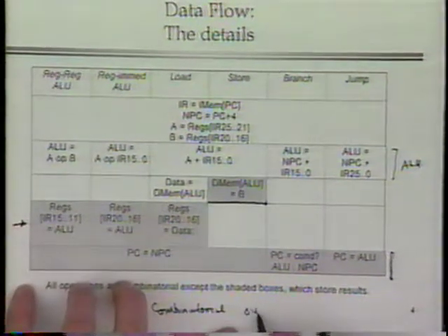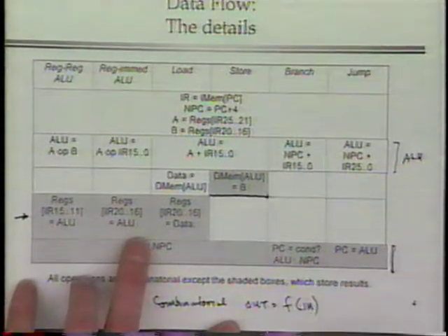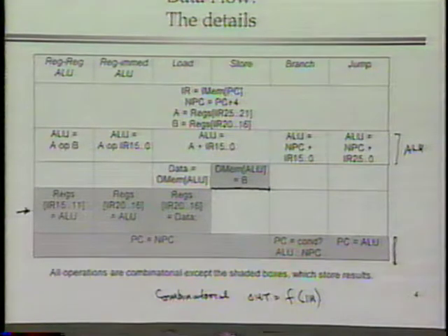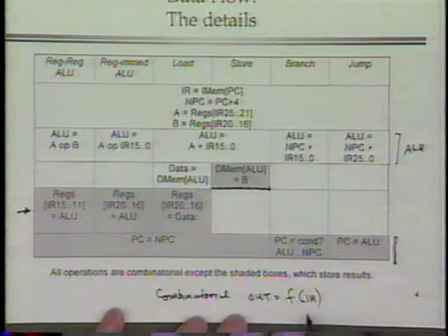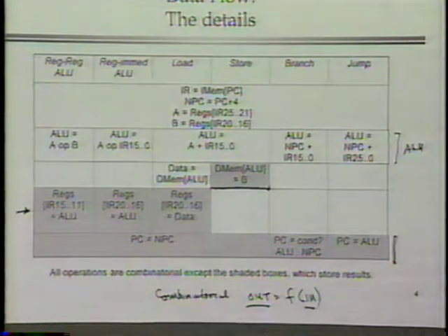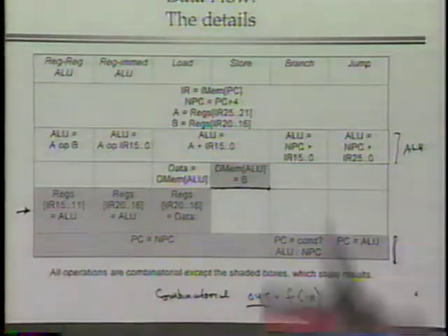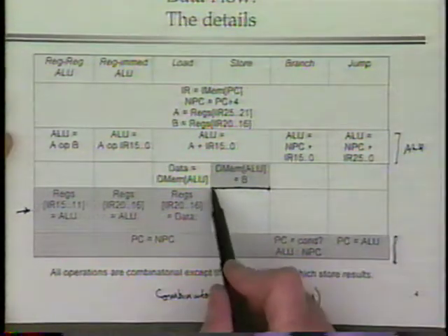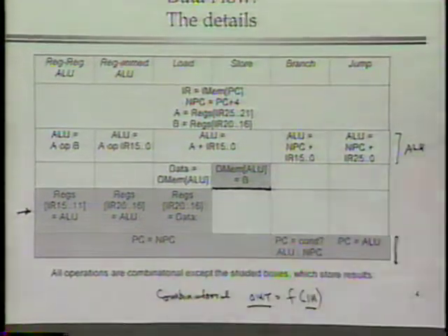is logic that is simply ANDs and ORs, basically. It's logic where the output is a simple function of input, and there are no clocks. There are no timing signals that are part of that combinational logic, and there's no storage as part of that combinational logic. It's just a function of the input that produces an output with no value stored and no clocks to indicate when things should happen. It's just sort of a bowl of spaghetti, and you drop things in the top and eventually it drips out the bottom. And the whole machine can be built like that, except for those times where you have to store something that lasts for a long time, like things you store in memory, registers, or the program counter.